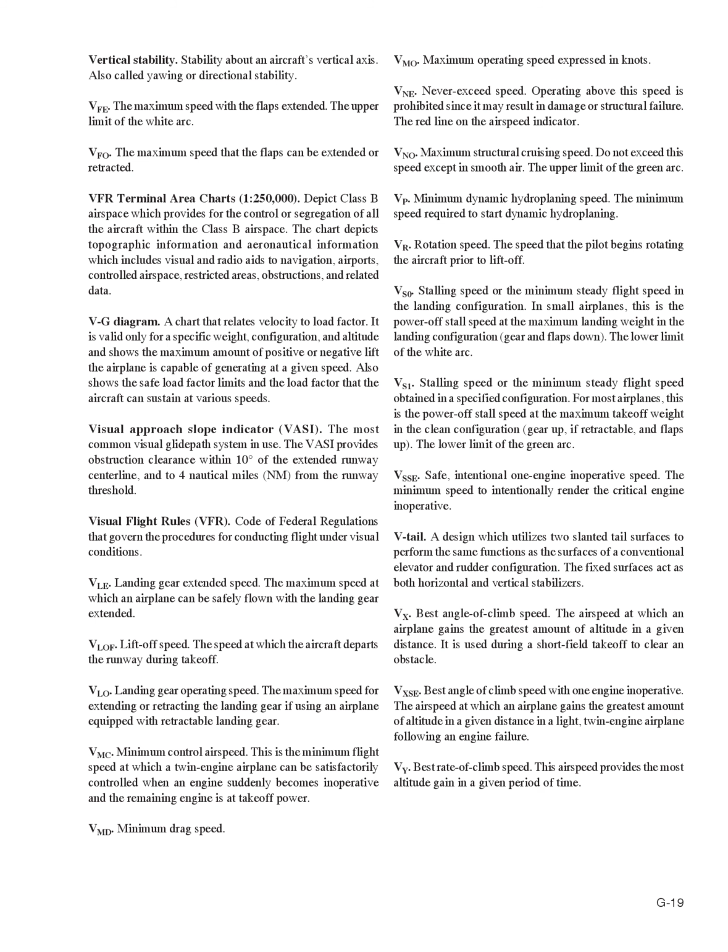elevator and rudder configuration. The fixed surfaces act as both horizontal and vertical stabilizers. VX. Best angle of climb speed. The airspeed at which an airplane gains the greatest amount of altitude in a given distance. It is used during a short field takeoff to clear an obstacle.